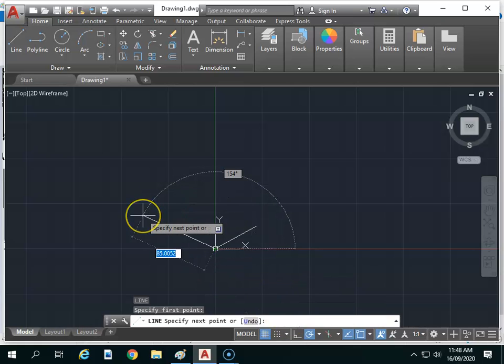But for the moment, we're going to type in 50 and then less than. Now, what angle do we want this to be at? For those of you who can see the board, there's a bit of a clue that it says, hey, you've currently got the line set to 154 degrees. So what I want is 180 less than 30. So what's 180 less than 30? Yeah. Or another way of phrasing that is 180 minus 30 is what I really meant to say.